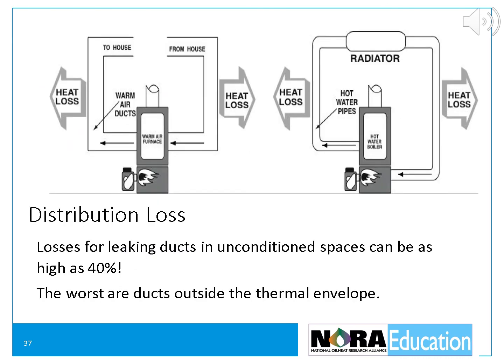Distribution system losses from pipes and ducts. The heat from a central boiler or furnace is transported to the home through pipes and air ducts. Heat loss that occurs between the heating unit and the living space causes system inefficiency. The level of heat loss depends on how and where the pipes and ducts are installed, the size of the distribution system, and the amount of thermal insulation. Uninsulated pipes and ducts that run through unheated areas have very large heat losses. A properly designed and installed heat distribution system can operate with very low duct or pipe losses.